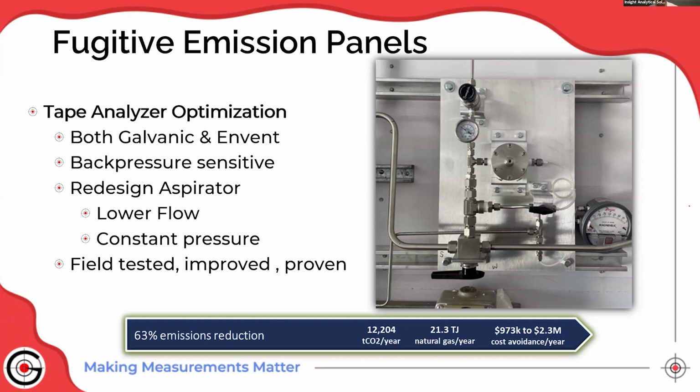Well, of course, in Canada, where it's minus 40, if you have a wet gas going out a fitting in the analyzer building, it freezes off. So typically, these analyzers will often have a natural gas driven aspirator that dilutes the wet gas with dry natural gas before it goes out the shelter so that the vent doesn't freeze off.